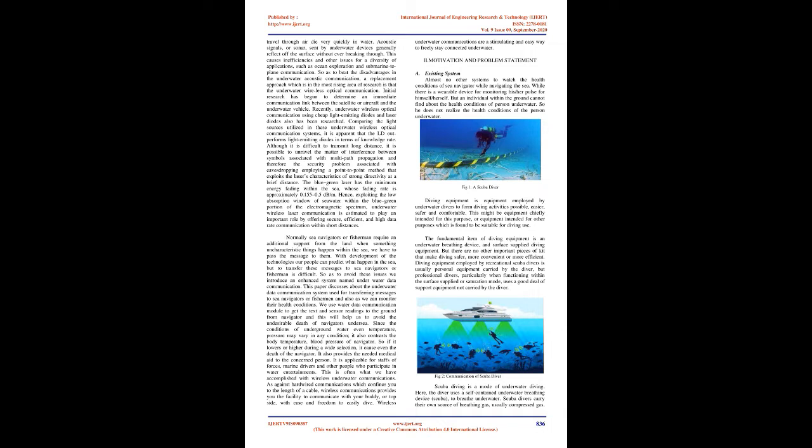Although it is difficult to transmit over long distances, it is possible to resolve the problem of intersymbol interference associated with multipath propagation, and therefore the security problem associated with eavesdropping, by employing a point-to-point method that exploits the laser's strong directivity at a short distance. The blue-green laser has the minimum energy fading within the sea, whose fading rate is approximately 0.155 to 0.5 dB/m.